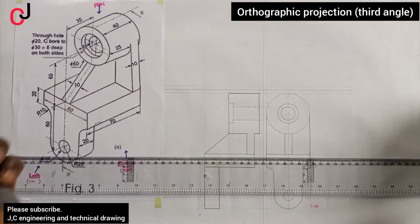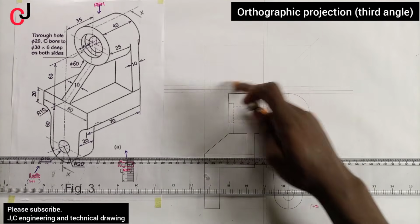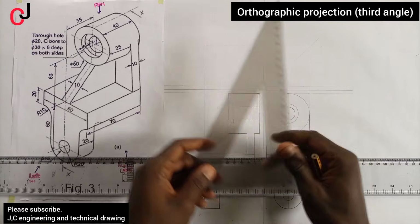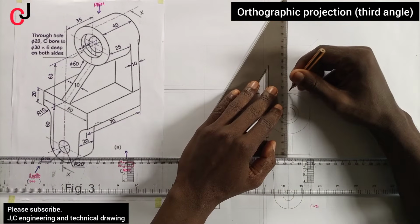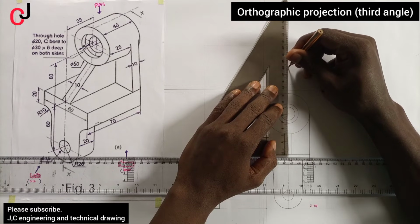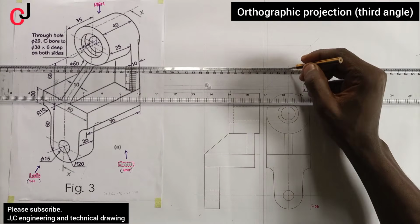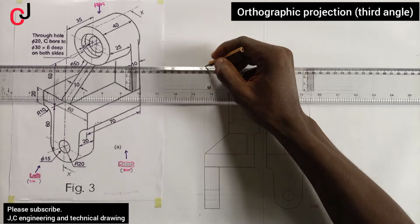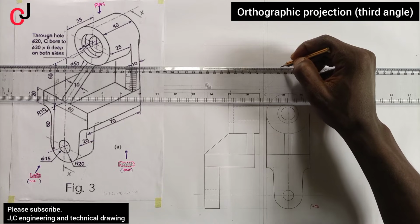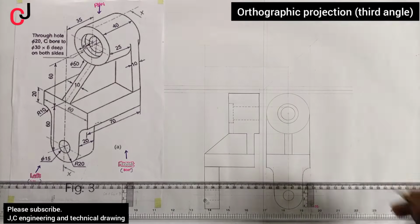Now if you check the plan from the top, you can see this shape here. So now what we need to do, from our center line, we project our center line also. Once it's at 45 degree, we'll project it to the left, indicating it with the center line. This way, all in construction lines.